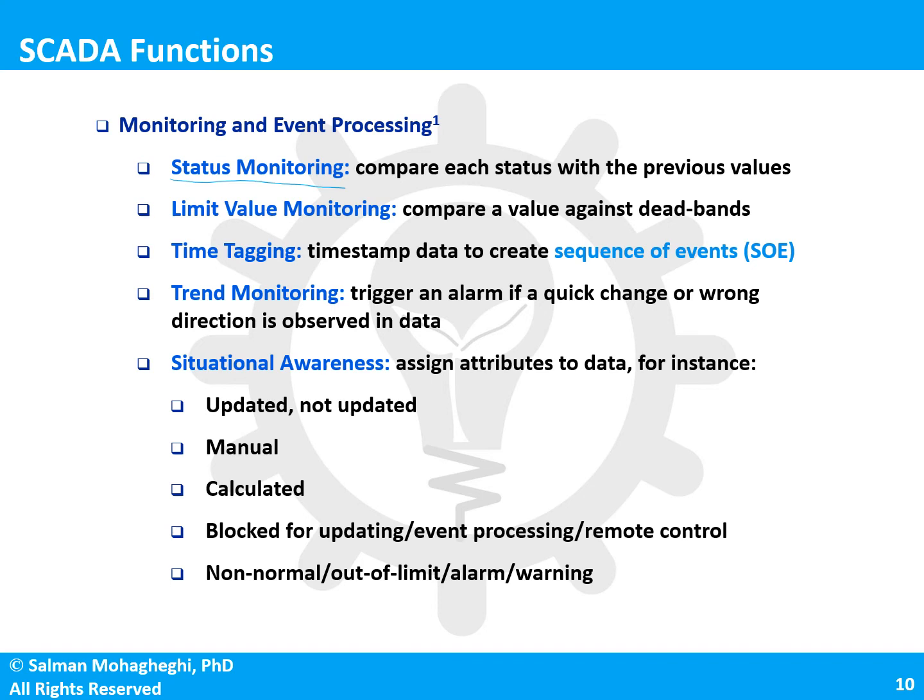It also allows us to have more of a general situational awareness by adding quality attributes to different data points. These are some examples here. For example, a quality attribute could be updated or not updated. If you receive a voltage measurement with a quality attribute saying this value has not been updated for a long period of time, that perhaps is an indication that something might not be right with that voltage meter, so you perhaps should not trust that measurement.